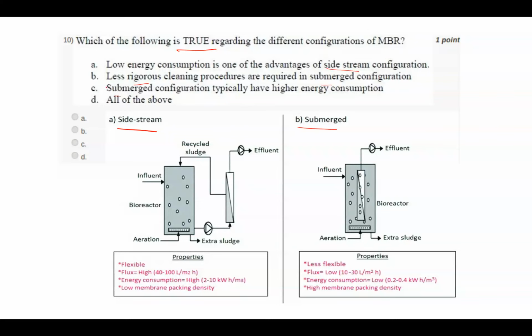Any answer? So the answer here is B. Less rigorous cleaning procedures are needed in the submerged configuration, which is this one. You can see here when we compare side stream and submerged configuration of the MBR, the membrane is fully submerged inside the reactor. Here it is separated.